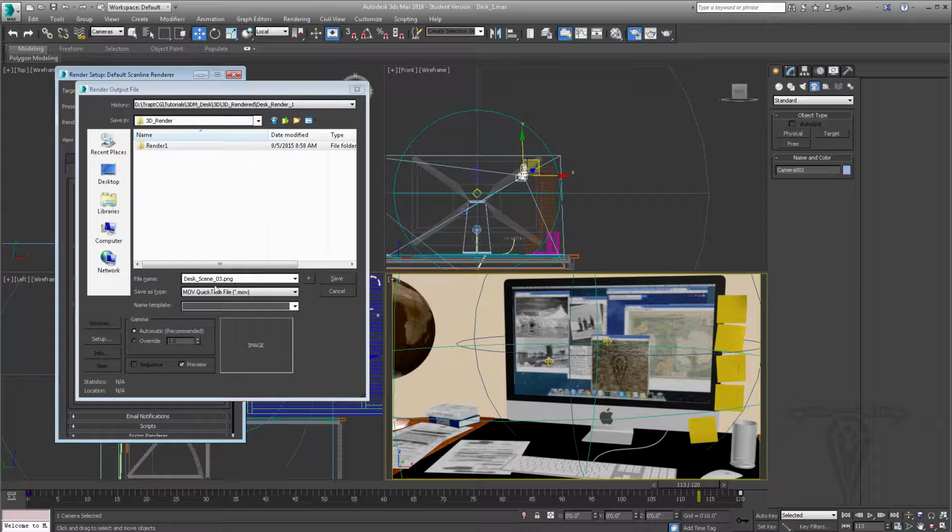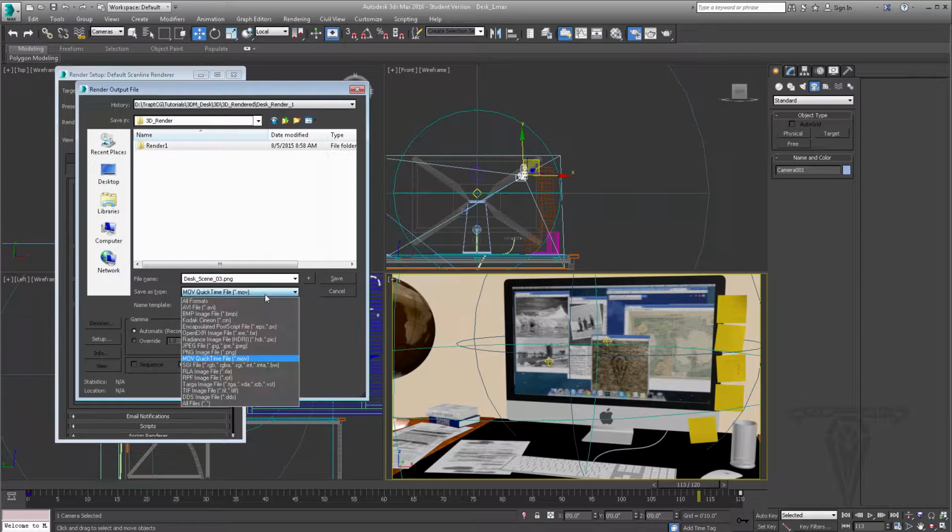All right, so like I said, I do not do movies. Primarily why is what happens if I'm rendering out this 120 frames and it gets to frame 119 and then the computer crashes. And it took 10 hours to do it. You just wasted 10 hours of rendering because you rendered out a QuickTime movie that just got corrupted when it crashed. So what we want to choose is an image file. It could be JPEGs, it could be TIFFs, Targas. I like to use PNGs.